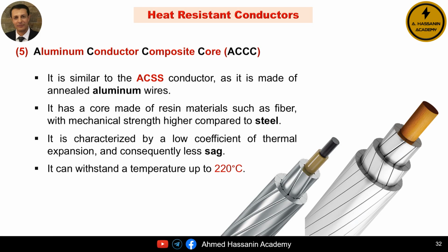One of the most important features of this conductor is its low coefficient of thermal expansion, which means that it does not expand at high temperatures, resulting in less sag even when temperatures rise. As mentioned earlier, this type of conductor can withstand temperatures up to 220 degrees Celsius.